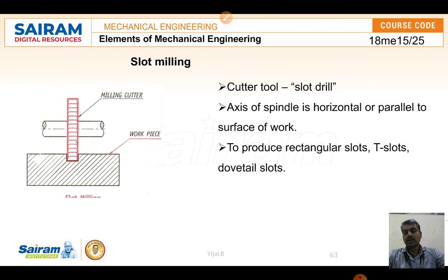Some other milling cutters are also used, where the cutter rotates in the vertical manner. And the slot milling cutters are multi-point cutters held on a horizontal milling arbor. When the horizontal milling arbor is rotating, the slot milling cutter is also rotating. When we bring the workpiece near the slot milling cutter, we can move it upward, downward, or longitudinally. When this slot milling cutter contacts the workpiece, it removes the unwanted material, so that we can make different types of slots in three-dimensional objects.